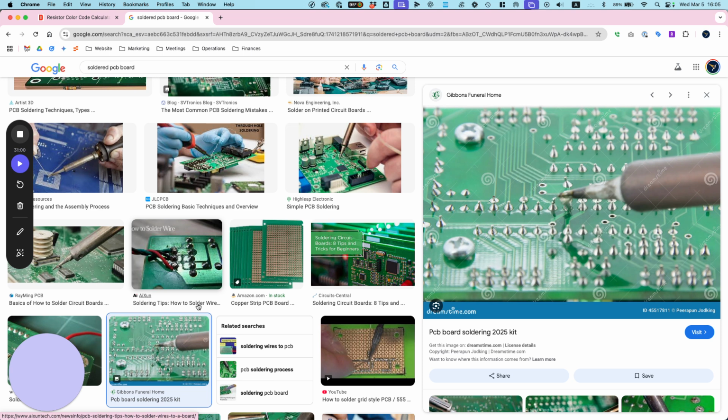If you recall, we're going to put it to this combo, and we're going to touch the function until it goes to the little audible signal. Then you can touch the leads, and make sure it makes a noise. Now these are too big to fit in there, so I'm going to put a wire in 5A and a wire in 5E. That way I can bring it out. Okay, and then I'm going to touch. It beeps. That's because everything's connected.